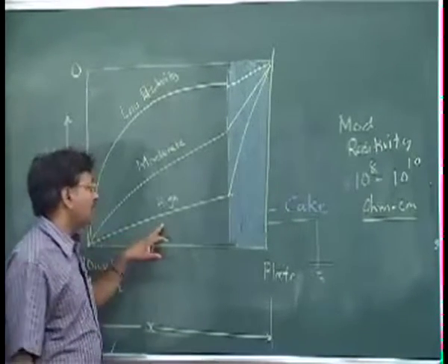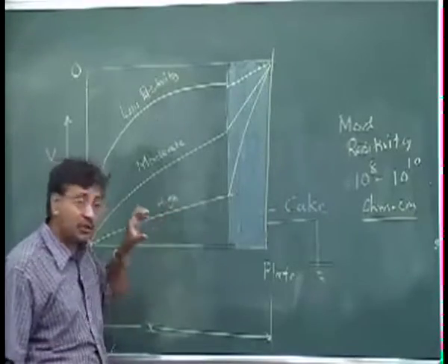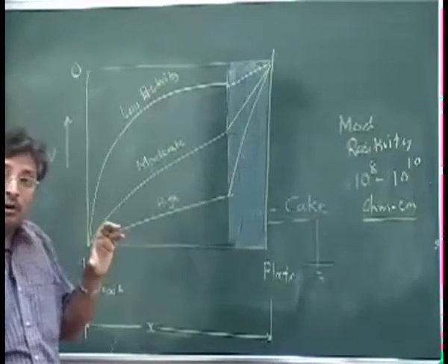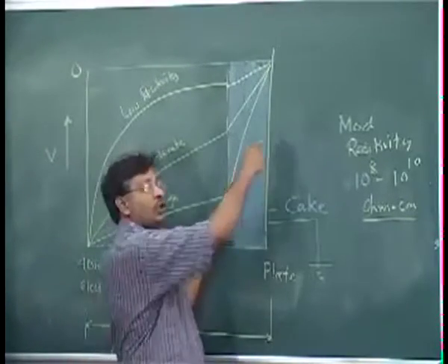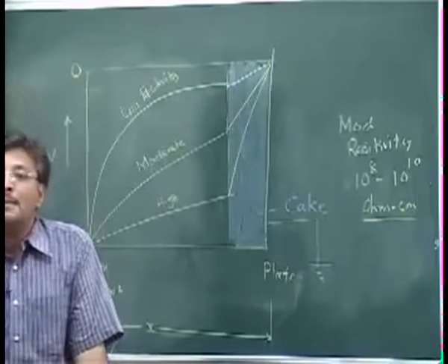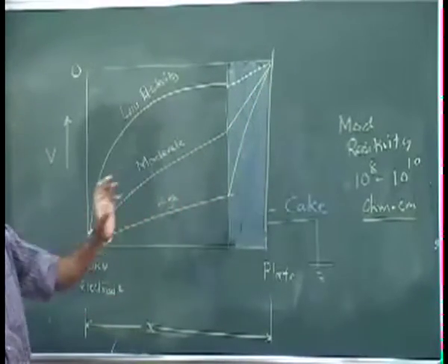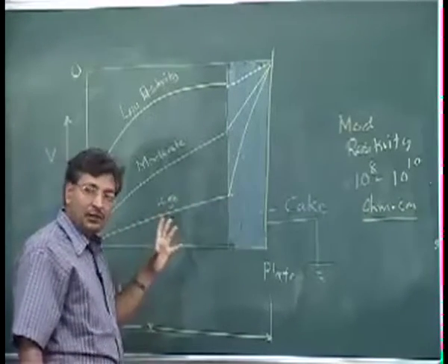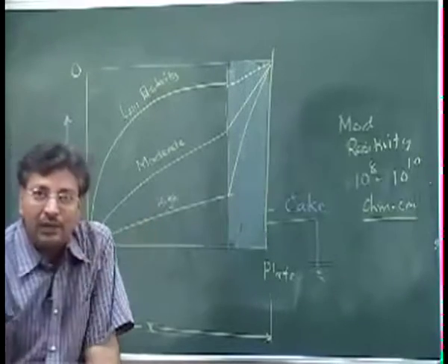Let us talk about the high resistivity. The problem with the high resistivity is that the particles or the gas may not have enough charge, the electrons may not be able to flow because of the resistivity they are showing. When the electrons are not flowing, they are not likely to hit the particles and go through quickly from the medium and stick to this one. The larger problem is the voltage difference. Because of this voltage difference, there is a possibility of generating back corona. The corona we developed at the discharge electrode can occur here, and then the particles will not only dislodge themselves, but there is another fear that it can catch fire.